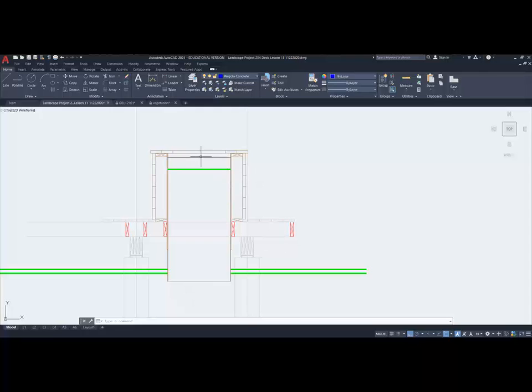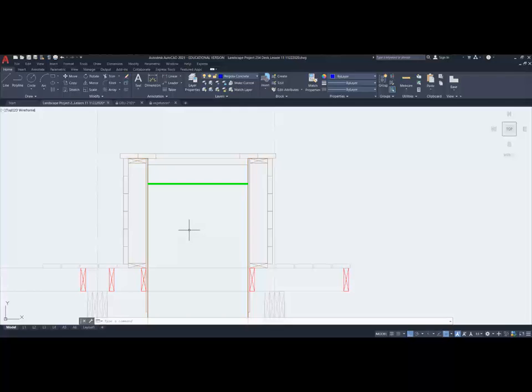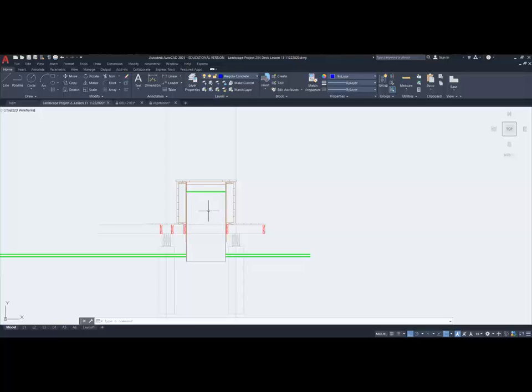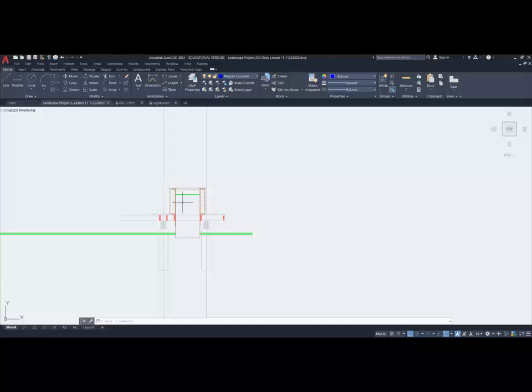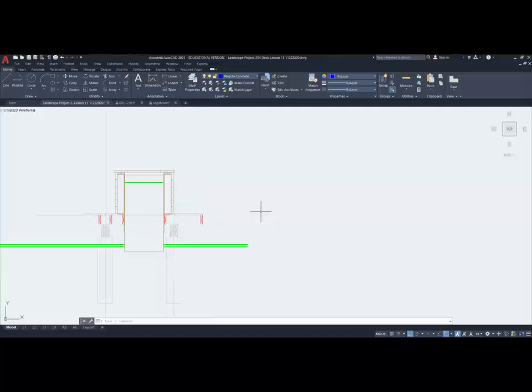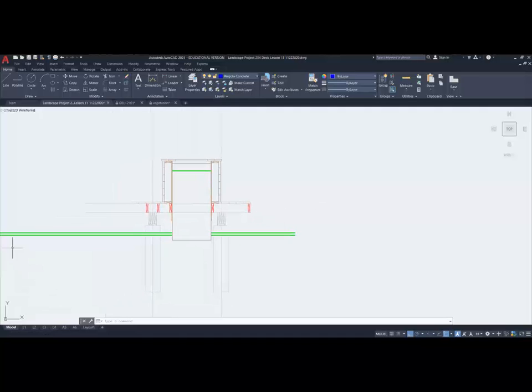So what else do we have to worry about? Now, if you're putting in plants there that will be there all winter long, you may want to insulate these two walls here and here, just so that the soil in here doesn't abruptly freeze and therefore damage the root system of the plants. So we could add insulation to this and everything else, but that's a section through your planter. That's what it looks like through there. We'll do a series of drawings where I'll show a basic section of the planter, lay out the top view, put all my reference bubbles, and we're ready to finish off with our planter details.